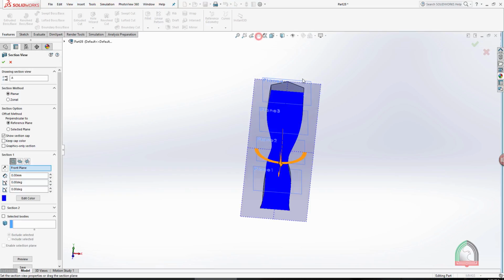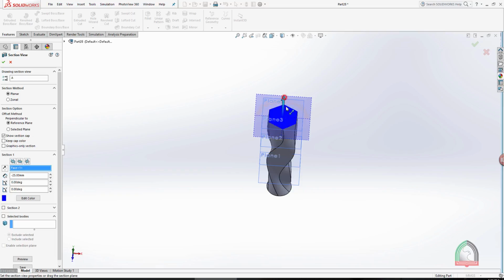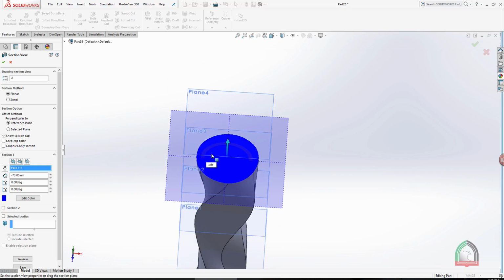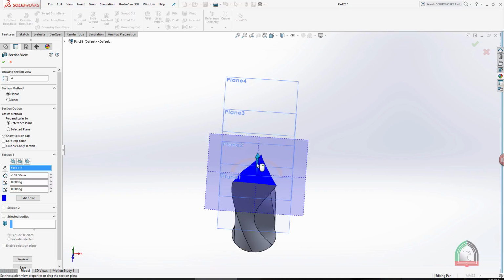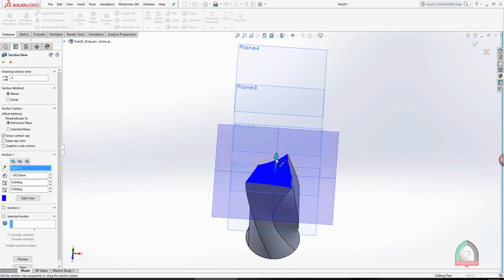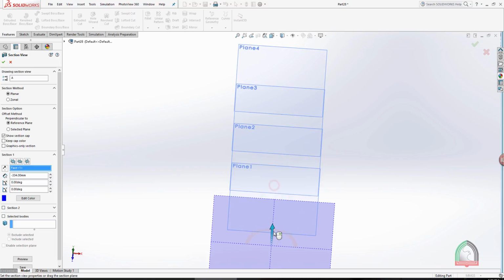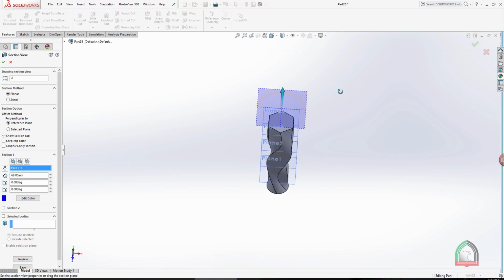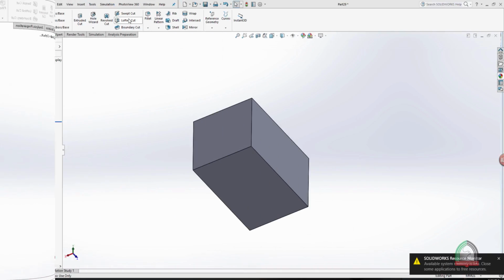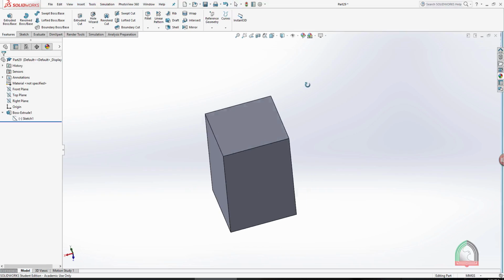Here you can see that if I am cutting from the top, it is starting with the pentagon. Now when we are moving down, it becomes the circle. Moving all the way down to make it as a triangle, then it is a rectangle, and finally in the bottom it's a circle again. So this is the one. If you want to merge anything together, we can use the same option. Now the lofted cut option, the same principle, but we can remove the material from the solids.